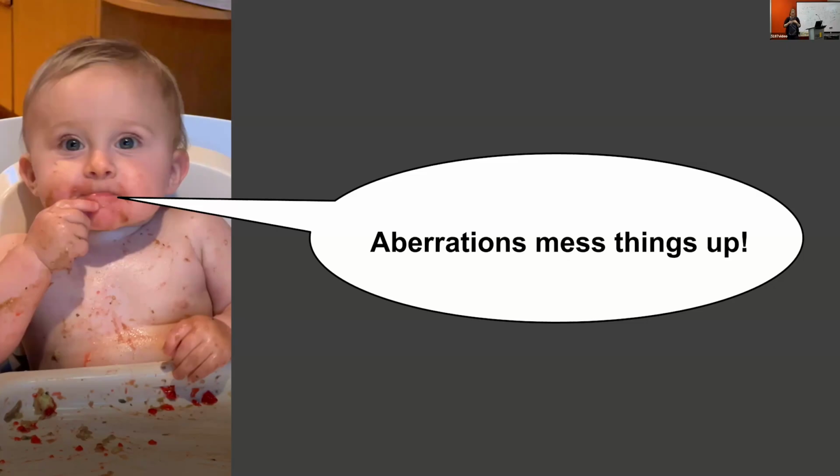If you want to do microscopy, you're bringing the object right up here and you have to think about high angles. All that microscopy stuff had a lot of problems because we're coming really close to the sensor, same design, but really close to the sensor. We have to deal with high angles. The sensor doesn't pick up light very well at high angles. It's not designed for that. That's one issue. We just sort of bottled that and dealt with it. But the bigger issue is that it becomes less and less shift invariant the higher the angles you go. If you come in this close to a sensor that's this big, then your angles are much larger than 40 degrees very easily, right?